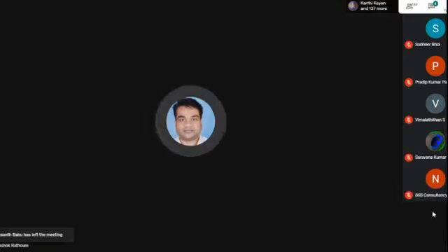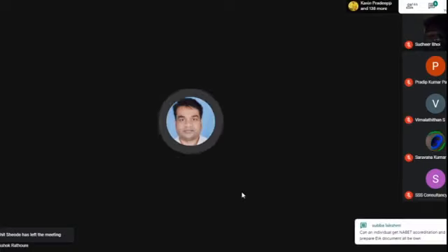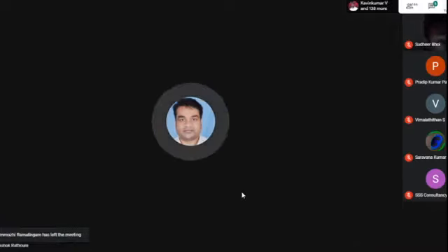Then you have to upload there by putting a remark, that is, for which study area, for which time period. The standard time period is from 1st April to 30th September, and the second period is from 1st October to 31st March. So that is the thing. You can upload online only on the Parivesh portal.